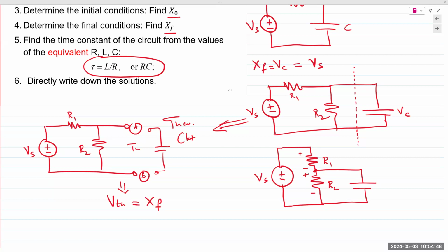Applications. So one of the most common examples I like to give is a camera flash. The big ones that are attached on top of a professional camera. Have you ever heard a whining noise in that flash? What is happening is there is a capacitor that's being charged from the batteries. Usually there are like 4 AA batteries, so 6 volts of charge that's supplied to that capacitor.